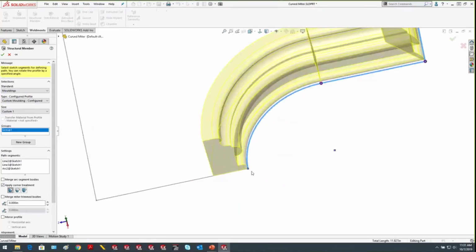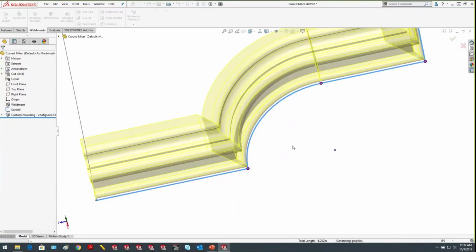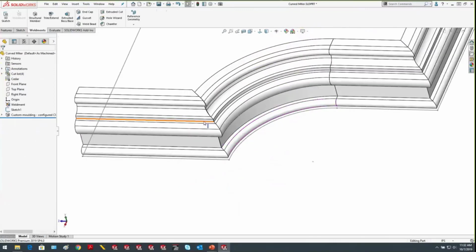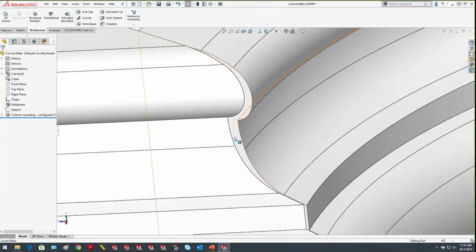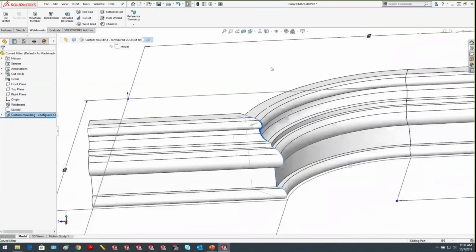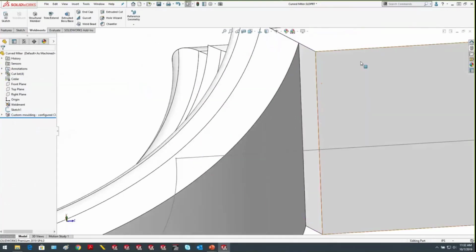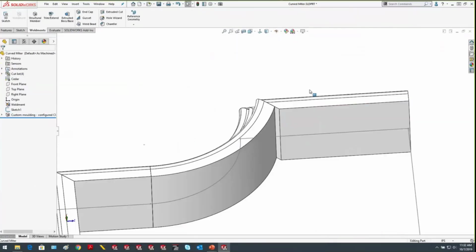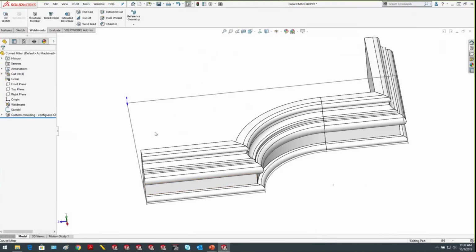But you'll notice down here I don't have a traditional 90 degree. So if I go ahead and choose this, SOLIDWORKS will create that 45-degree miter. And if I create it, in this case, if I look at the area where it meets up, that is not a very clean miter. And if I look at the back, it becomes a little more obvious where those just don't match up right. So I'm going to have to go through and create my own miter, essentially.